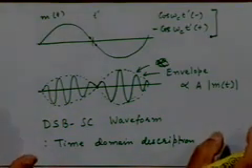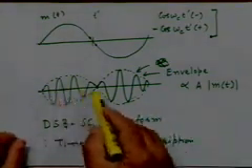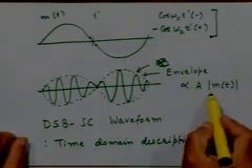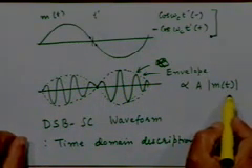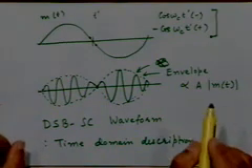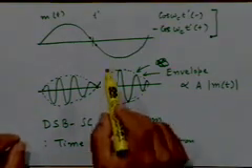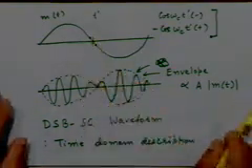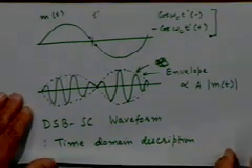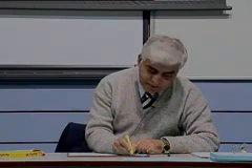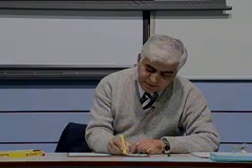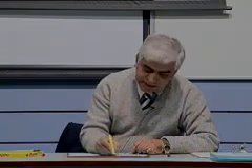The important things that we have learned here are really two. The envelope of the DSBSC waveform will be proportional to A times the modulus of the message waveform m(t), and the second thing is that at the points of zero crossing of the message waveform the carrier will go through a 180 degree phase shift. So these are the two basic characteristics of a DSBSC waveform. Now let's look at the same waveform in the frequency domain by looking at the spectrum of the DSBSC signal, which is a fairly straightforward exercise.